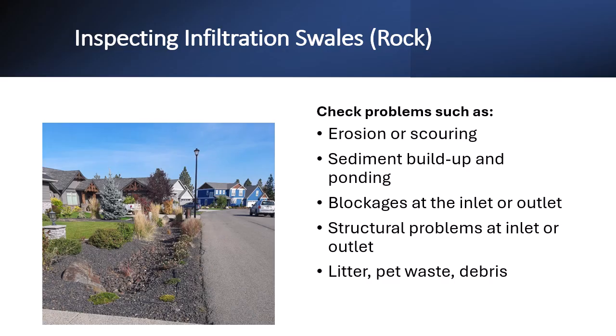Again, note that it is not enough to have a clean or open inlet or outlet structure. If sediment buildup around the inlet impedes flow, this can cause problems such as water backing up into the road. If sediment builds up around the outlet, water may leave the swale more quickly. Structural problems at the inlet or outlet include any damage, settling, or misalignment that could disrupt function.